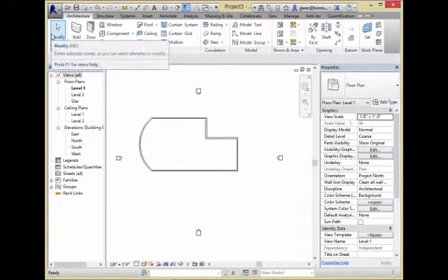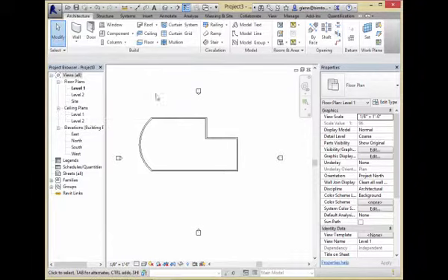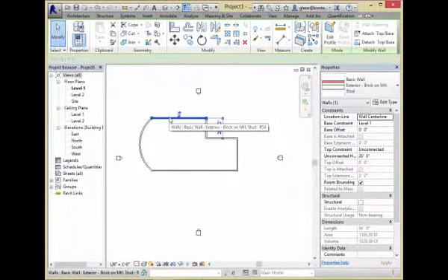Actually, as I've been drawing the walls, you'll notice I've been sloppy about this in that I didn't pay much attention to the height of the walls. Those are going up to this unconnected height of 20 feet. Probably not the best choice, so let me go ahead and fix that. I'm going to want to make them all go just to level 2. That'll be a little bit stronger.